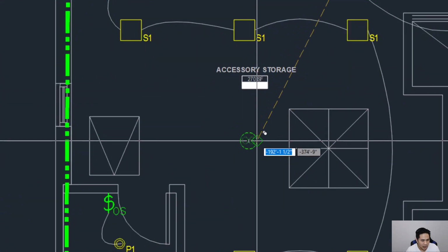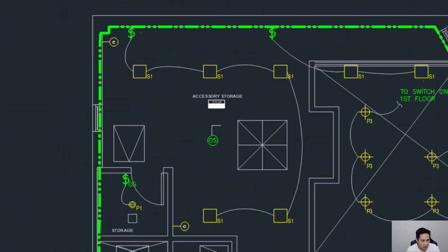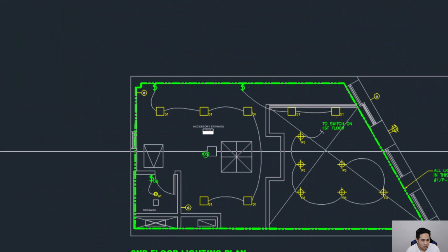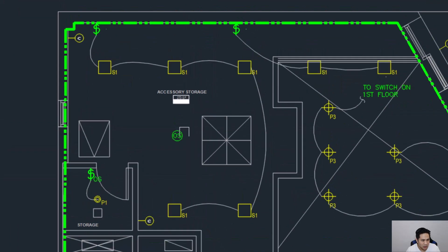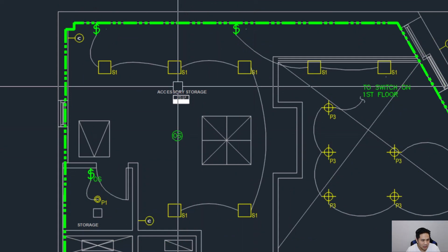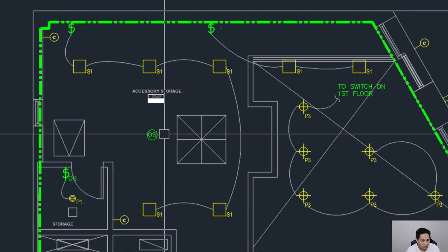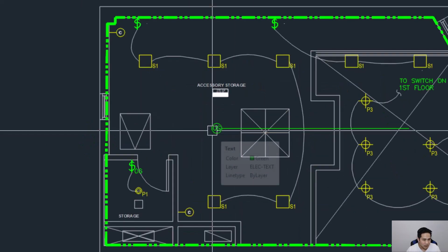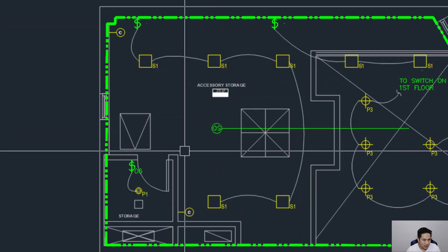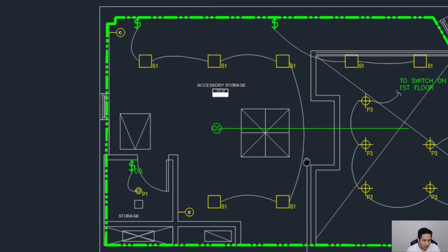right here. And the occupancy sensors, you should give it a range or coverage area about 15 by 15. So it's going to be 15 on either side. So basically it'll be 15 this way, as well as this way, and this way.